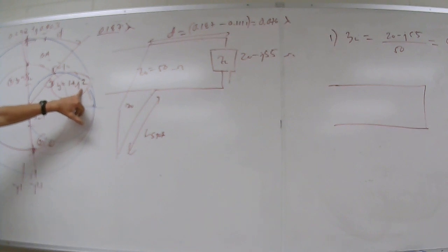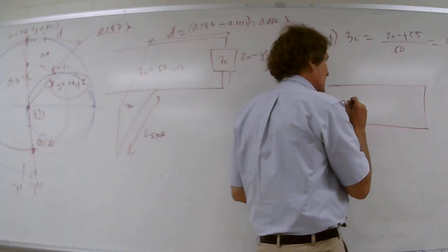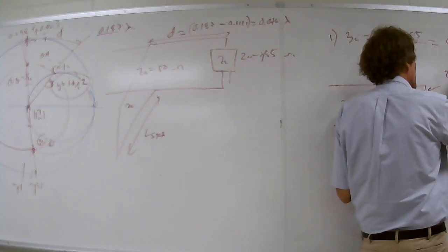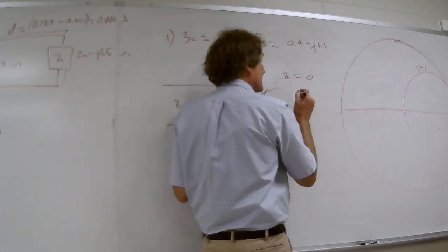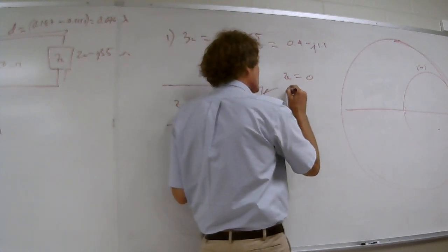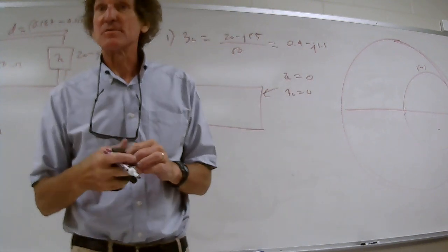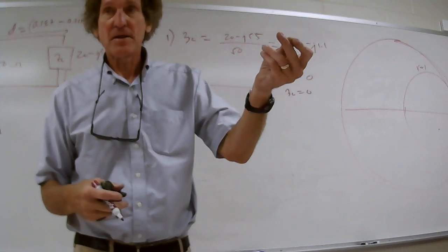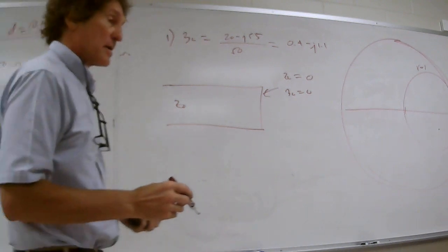Do you all follow the trick here? Right? It's admittance. So, come over here. This is Z naught. Now follow me. What is the impedance of the load? If it's a short, 0. Take that and normalize it. What do you get? 0. All right, now take 1 over that. Now you got the normalized admittance. What do you get? Infinity. Infinity, correct class? Where is infinity? The right side. It is right here.